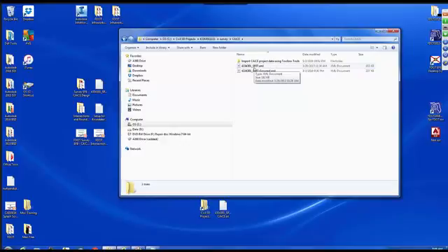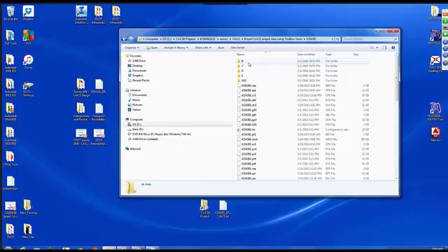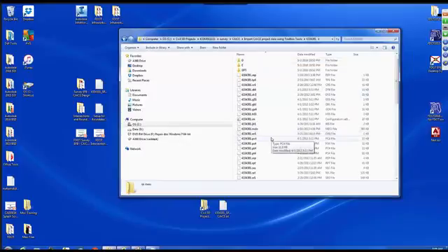All right? So they bring the data into CAiCE. They work with the point data, they create alignments, they create surface, they do all their editing and their cleanup, and when they're done, they export out this LandXML file. Okay? Now, I have another folder in here that has the actual CAiCE project. And in there, I have all the different files that I need. Remember, I was saying that in order to bring in a CAiCE project, we need a PT4 file? Well, there it is right there. So this is the data that I'm going to be working with today.